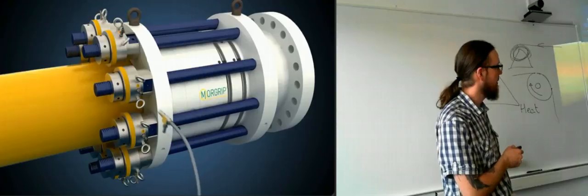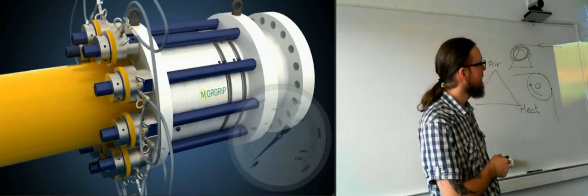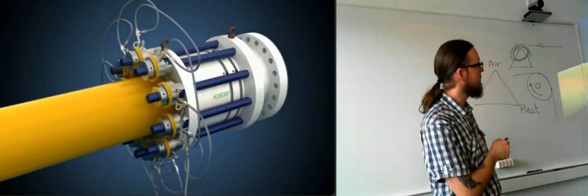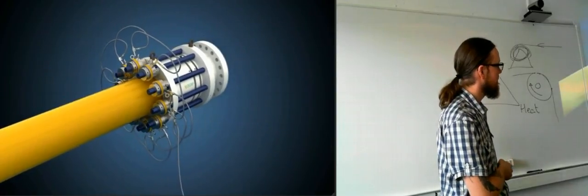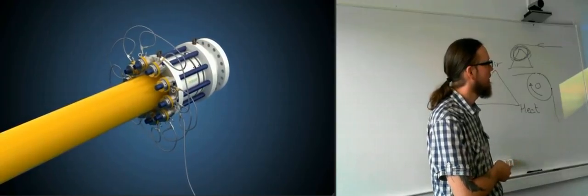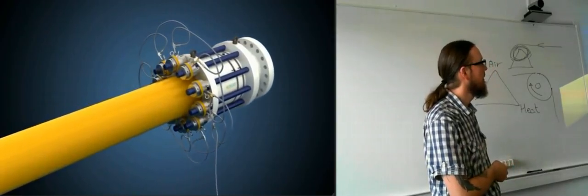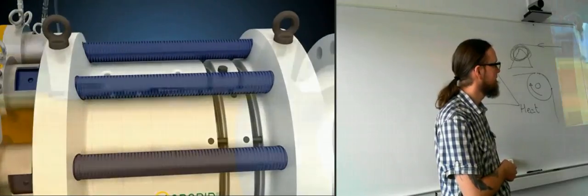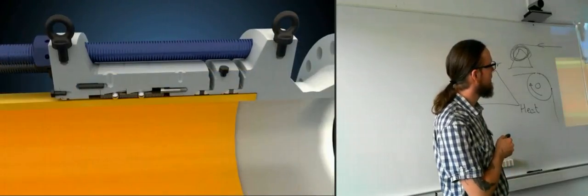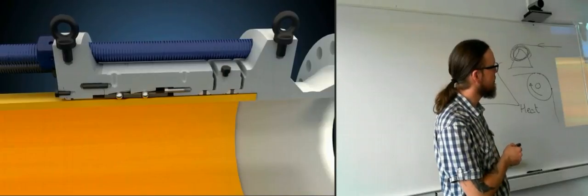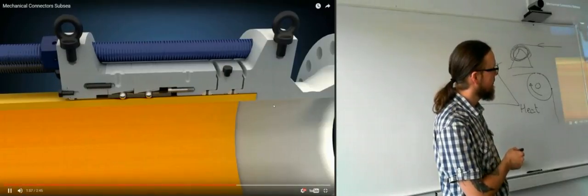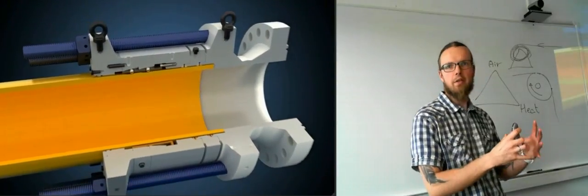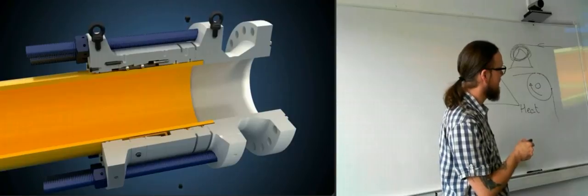Connect with the hydraulics for here. So they have one connection going to the supply, and then they have just looped it around to all of them. And now what they're doing is that the hydraulic system is turning these huge bolts so that they are compressing everything here, which means that it is sort of pulling everything tight, and then you get a really tight seal here.